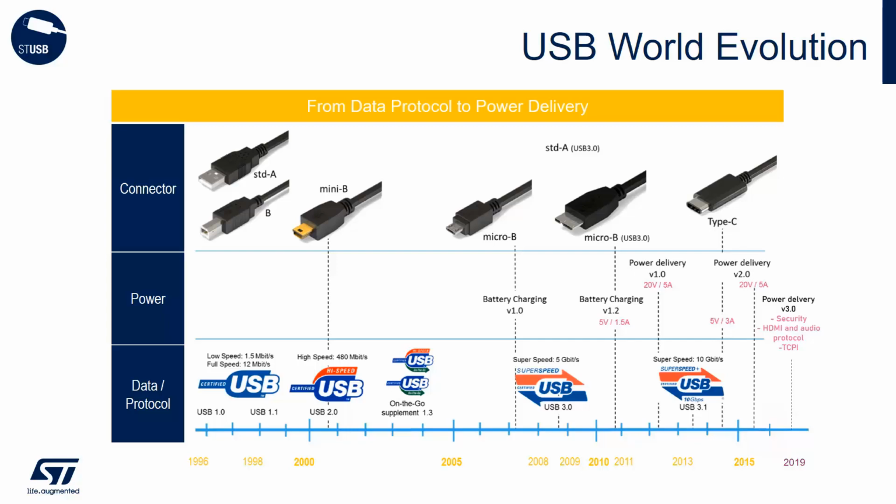In 2001, the USB-IF ratified USB 2.0, which increased the data rate to 480 megabit per second. We also witnessed the introduction of mini and micro connectors for the device side of the cable to replace the larger Type B connectors, and this was an important development for space-constrained portable devices. In addition, the On-The-Go supplement made it possible for two USB devices to communicate with each other without requiring a separate USB host to coordinate.